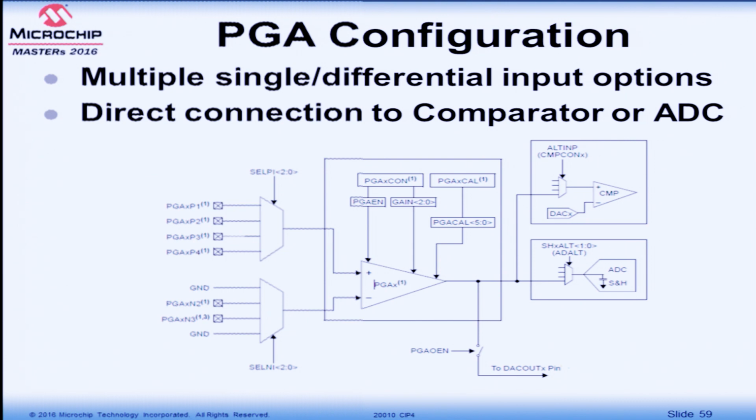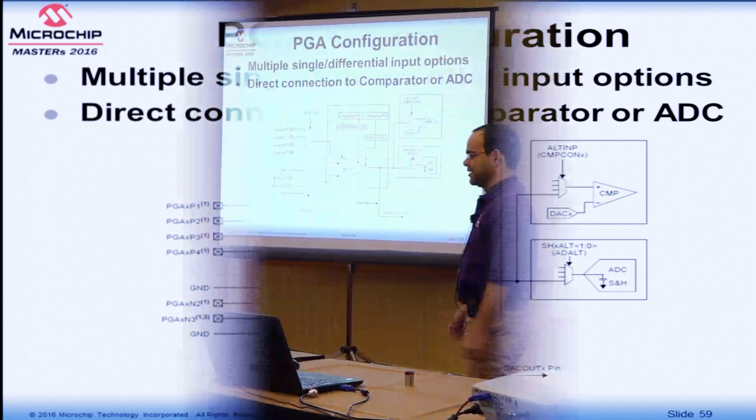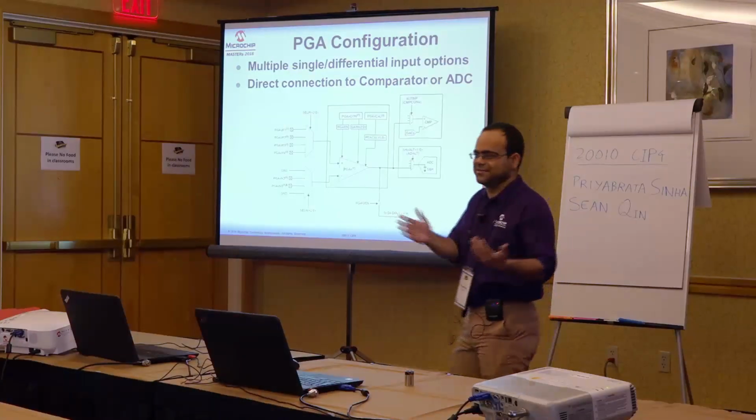During production tests, some values are stored in the flash memory area or test memory area. All your production code needs to do is read those values and write them to that register, and it will self-calibrate itself. That's to account for the process variations between devices.